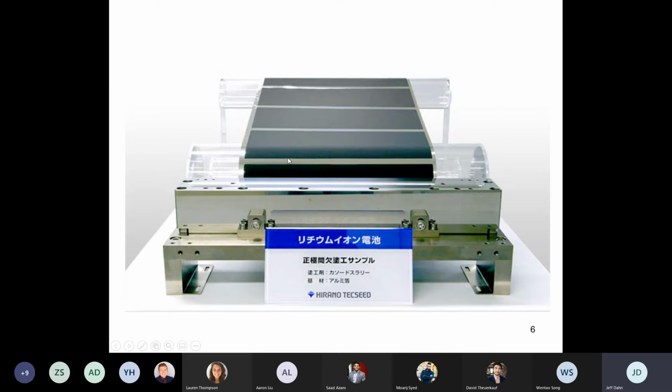Electrodes for pouch cells and cylindrical cells are often patch coated. So what that means is you have coating for a while, and then the coating head lifts, and there's a bare foil part. You need this bare foil to be able to attach electrode tabs.